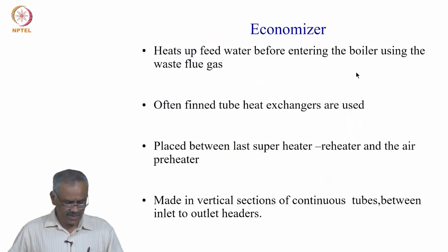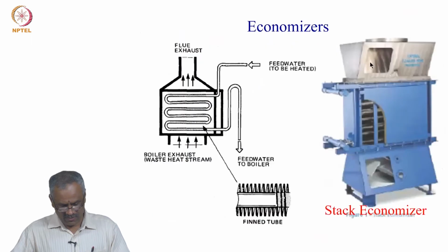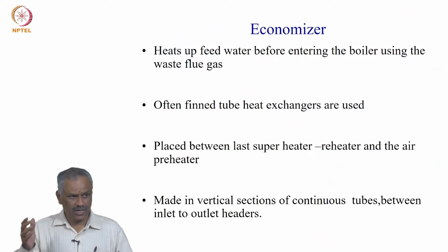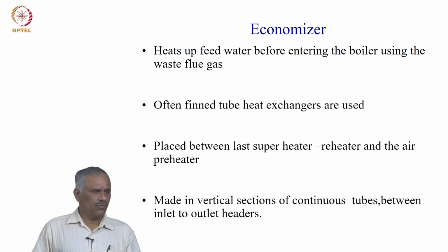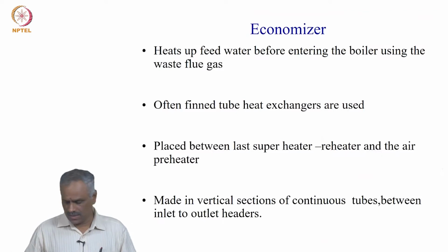Today we will discuss the economizer, and we also gave some background details here. The economizer is generally used to preheat the water before it enters the boiler evaporator. This economizer makes the exit condition of the economizer equivalent to the saturation condition.